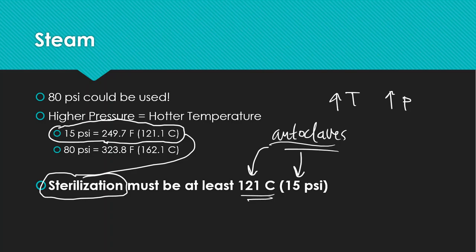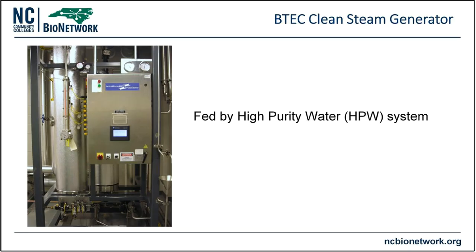So as you can imagine, if I've got these vats and these vats need to be sterilized, I'm going to put some steam into them. The vats need to be closed off. The vats need to build up pressure. That pressure needs to be 15 psi, and it needs to hang out there for a little bit. And the temperature on the inside needs to be around 121 degrees Celsius. If not, then sterilization is not really being followed. So those are going to be the two regulatory pieces that we need to monitor and track throughout the sterilization process there. All right.